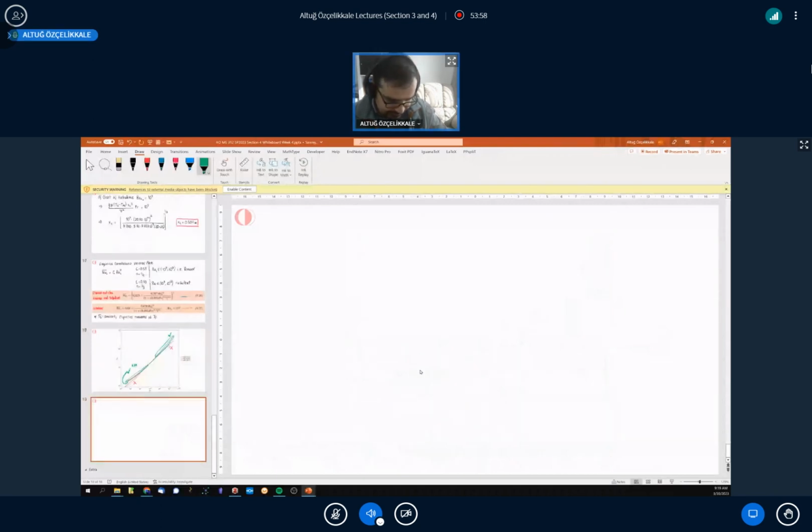Okay, so the other thing we discussed was that these correlations are for constant surface temperature. We can have an electrical component that's being heated by uniform heat flux, right? It can be a power system, again, that can be heated inside by the electrical circuitry. Then we will talk about heat flux that's constant across the board. And how are we going to cool that down with natural convection when you have no means to actually induce flow within the enclosure, let's say, or it's simply open to the atmosphere like that, vertically.